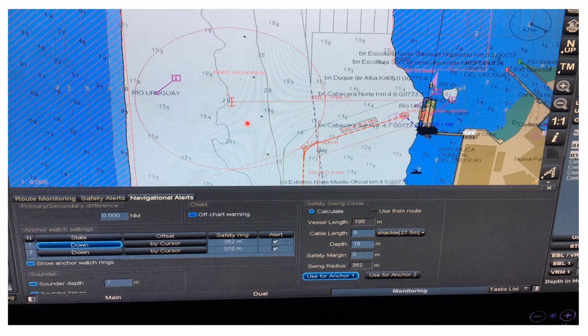So it's very useful. Then once you arrive here and drop your anchor, you press down so that the bow of the vessel and the position of the dropped anchor will be the same in the center. Then you will have the same swinging circle like this one.